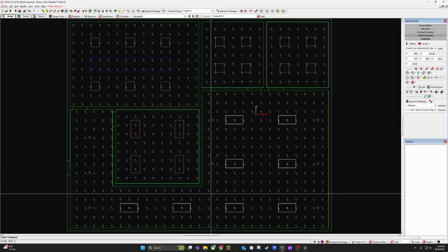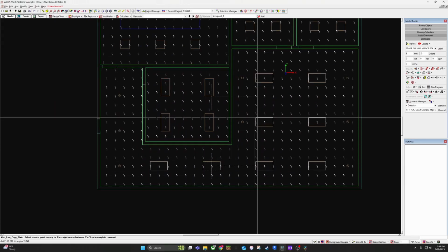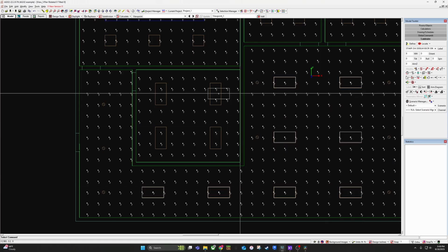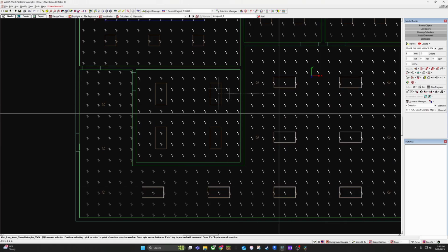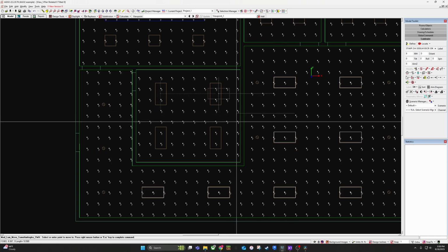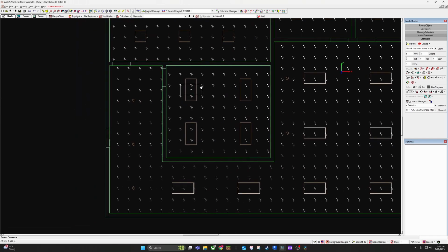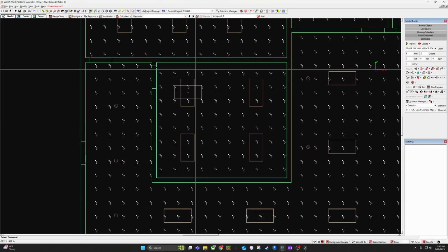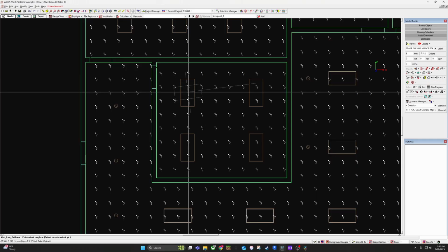Great. We need to move a light up here. We'll copy one, then if you want to move it, choose the arrow. Same thing as always, right mouse click to proceed with the command. Now, we gotta turn this one 90 degrees. I'm gonna go reorient, click it.